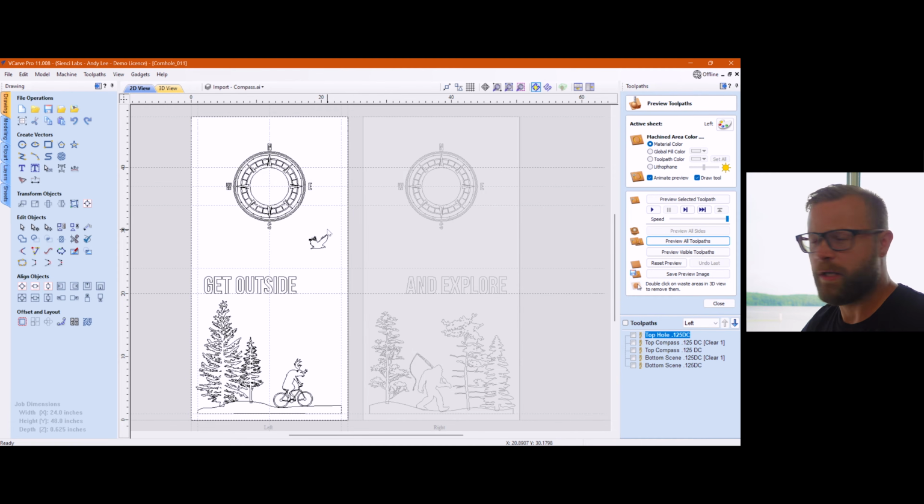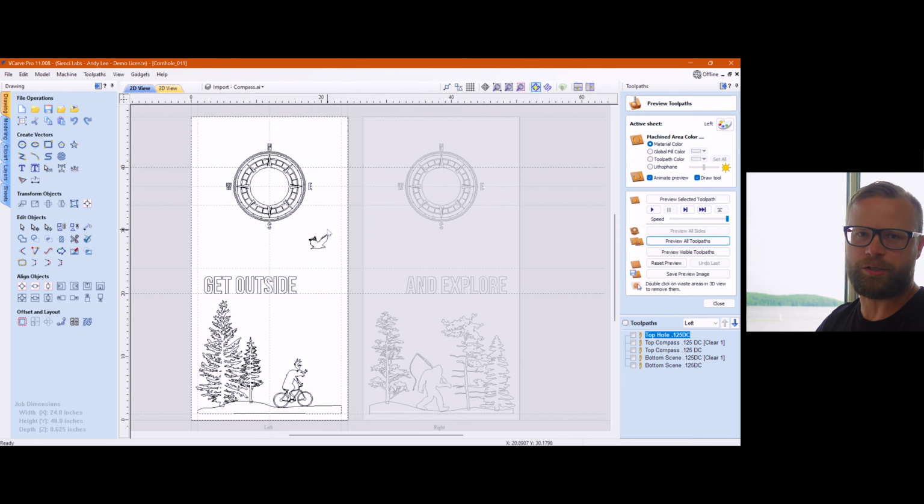Yes, materials. So I've made a couple of these already, so I had a pretty good understanding of how to put them together. I've made them a few different ways. This is the first time I've actually used full-out plywood like this. The last couple I did, I used recycled fence boards, quite honestly, because I wanted a vintage, more antique-y feel. This one was straight 5/8 plywood. I used 1x4 solid pine for the sides and the frames and the legs, and that was about it. So from a material standpoint,